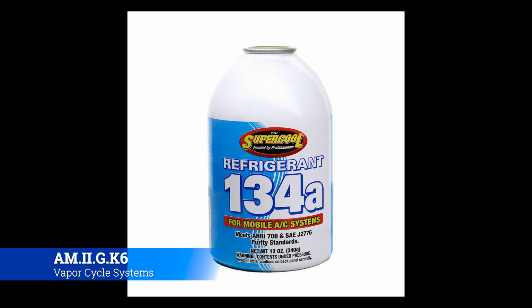Reason being is back in the day, there were guys that would work on this type of stuff, and they would just open it up and just let it blow all out of the system, and that is one of the things that really depleted a lot of the ozone layer. As cliche as that may sound, that was a serious problem back in like the 70s and 80s, and so enforcement came in, and then eventually they started trying to come up with a new refrigerant that didn't have the same sort of effect. And that's how you get our 134A. Now, the downside is they've ramped up the price of all that refrigerant significantly in doing so.